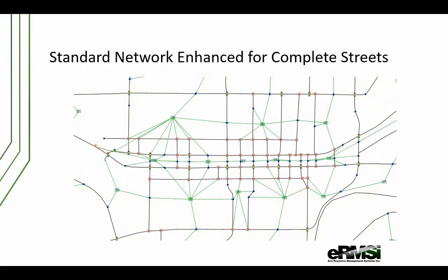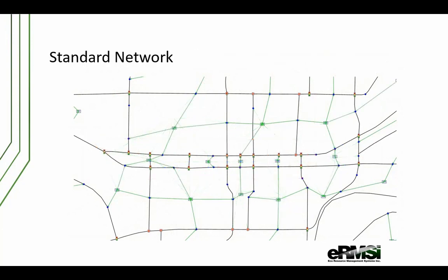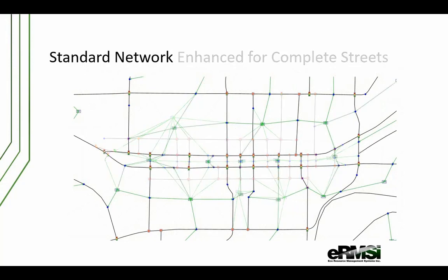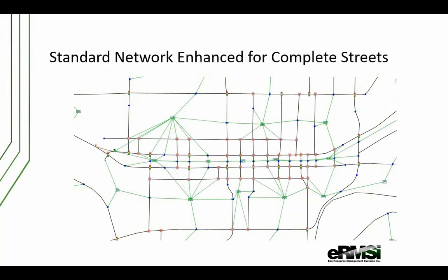To include the alternate routes, I did not include the background here because I thought we had enough to look at as it was. However, we added in more network nodes, links. Note that in these Visum models we include all of the intersections and controls and so forth, geometrics, and so we can do the LOS analysis there with the ICA.